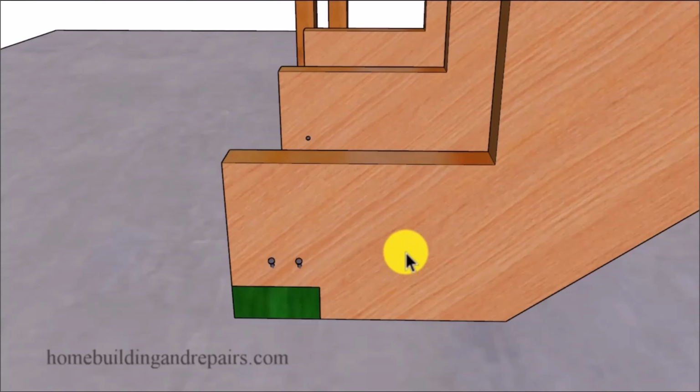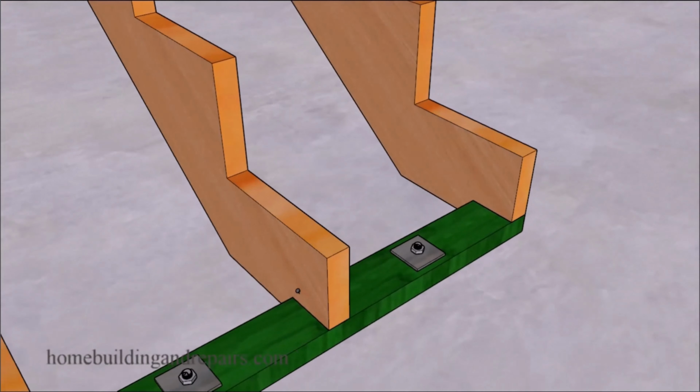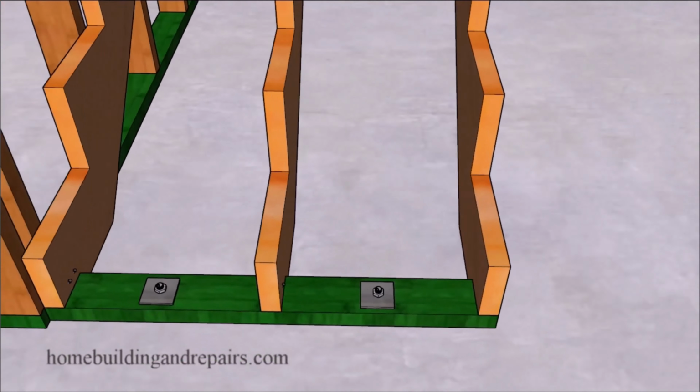Something like this might work fine on a wood-framed floor, where you can drive more fasteners through the stringers into the wood-framed floors, or even use framing hardware. On a concrete slab, you can see where you're only going to be able to attach it to the base framing plate, not to two base framing plates like you would have seen in the previous example.